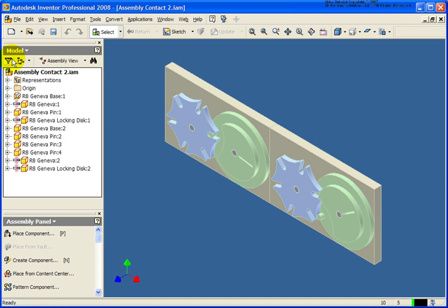Also, from the Model tab here, let's work our way across. We have a browser filter. And in this case, we can go back and remove objects from the browser. Some of the browser information with larger assemblies can get very complex, so you can go back and remove those. The next option here, again, is going to be our design views from our drop-down list. In this case, we don't have any besides the master set. But again, we'll cover that in a later lesson.